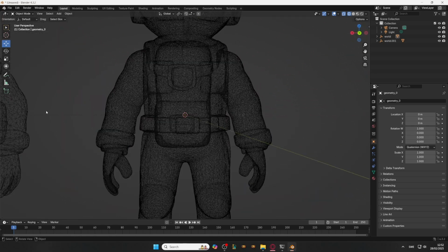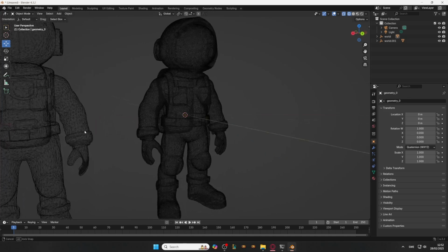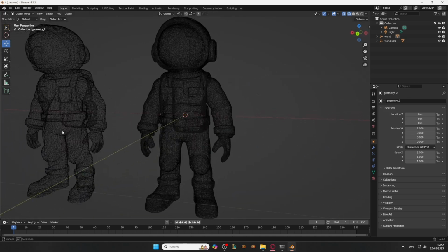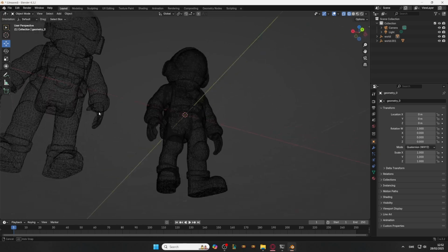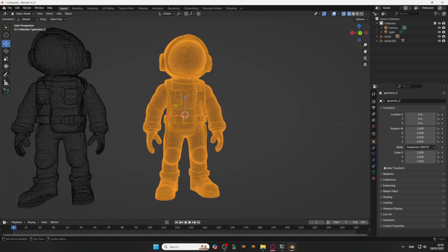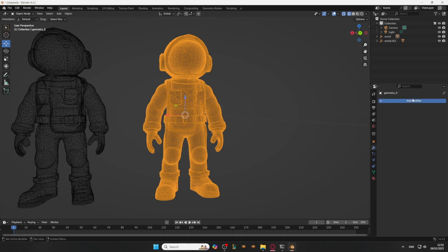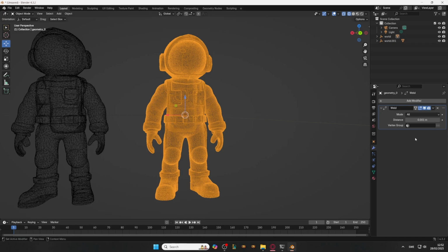Okay, so if I went and remeshed this immediately, there is a possibility that some of the vertices are not welded to each other. So what you need to do is select your model, and then go into modifiers, pretty much, and then add a weld modifier and put it to the minimum setting, so 0.01.